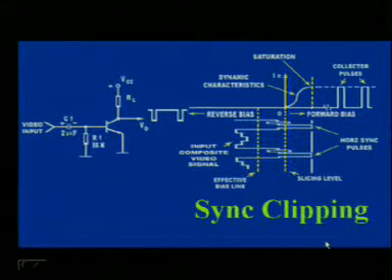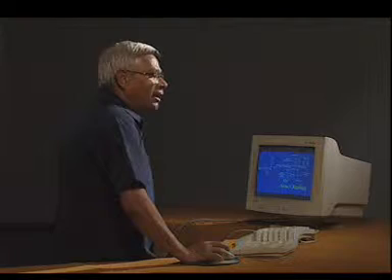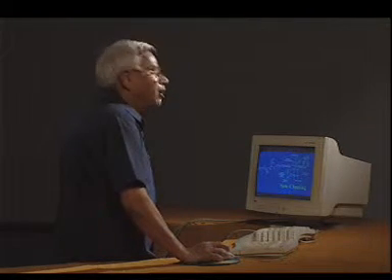Let us see here the working principle of sync separation. This is a video signal of 100% level, out of which the 25% level of the sync pulse is to be cut. And how to cut? The sync separator transistor is biased, and the biasing is done between the collector current and the collector voltage. In the linear portion of this curve, these pulses bring the transistor into conduction and the sync pulses are clipped and available for the horizontal oscillator or for the vertical oscillator.